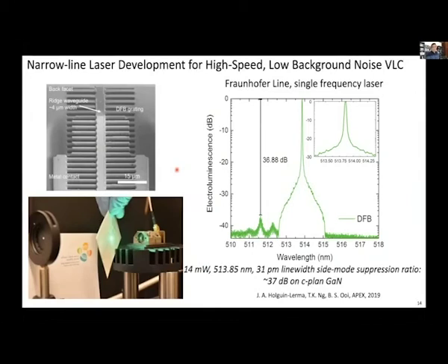In gallium nitride, we all know that it's quite difficult to fabricate and process the gratings and make any small features onto gallium nitride; it is highly challenging. In our case, we start from a ridge laser and then place the surface grating, a very high order grating. Although we lost a lot of power by using a high order grating, we managed to at least be able to write it by using focused ion beam to control the wavelength.